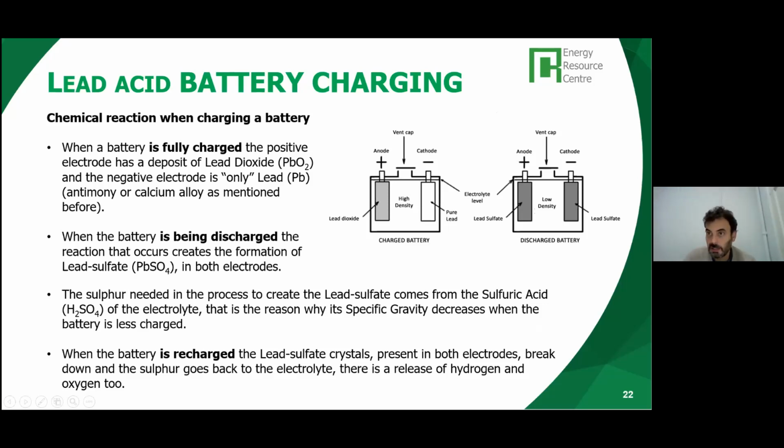There's less acid in the electrolyte, so it's mostly water, and these sulfuric ions start depositing on the plates. When the battery is recharged with the supply of electricity, the lead sulfate crystals deposited on the plates break down and dissolve again.